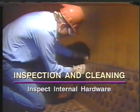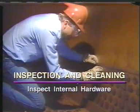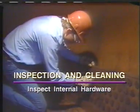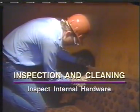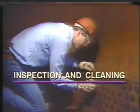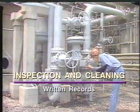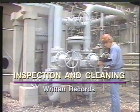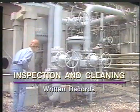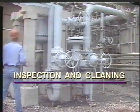While the tower is open for repairs, the vapor and liquid paths should be inspected to make sure they are free of obstructions. Downcomers and bubble caps should be free of solid deposits. Even a partial blockage of a vapor or liquid path will cause inefficient tower operation. A list of scheduled repairs is normally compiled prior to shutdown. Any other problems that are discovered during the inspection of the tower are then added to this list. By keeping thorough written records, we make sure no necessary repairs are overlooked.